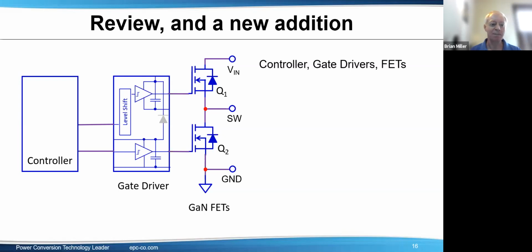No load, I've seen cases where, yeah, you can have some things happen. There have been some odd situations. The assumption through a lot of this presentation is a somewhat standard half bridge, where the switch node goes to an inductor and then to something else, probably a capacitor or a transformer. To have a true open circuit and running at high speed, yeah, there might be some.